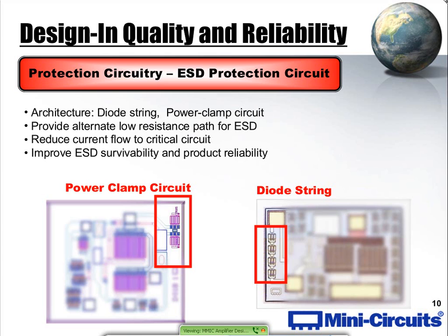A device that is damaged due to ESD may not show up as an immediate failure in test. It may not even show up in the first week, or the first month. It could present what everyone fears in terms of a latent defect that may manifest itself years down the road, and you don't know about it as the designer or the manufacturer, because you can't test for it.